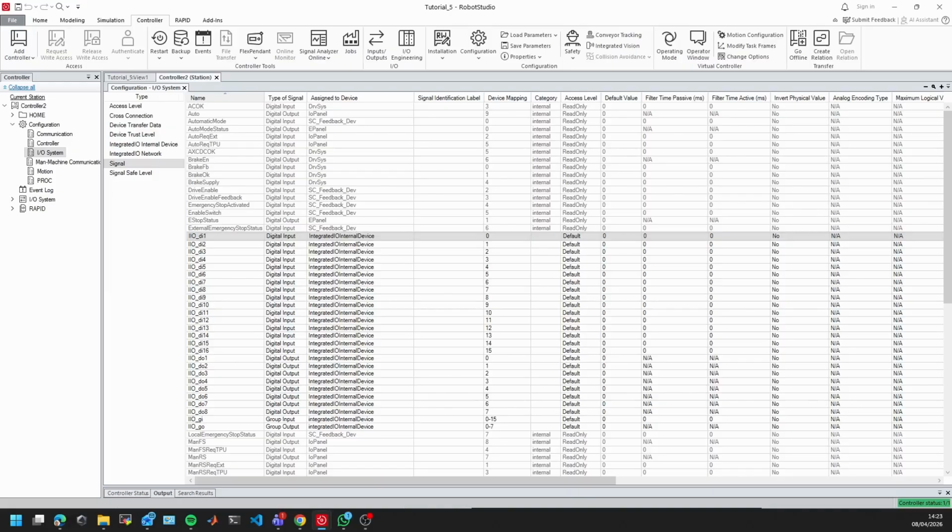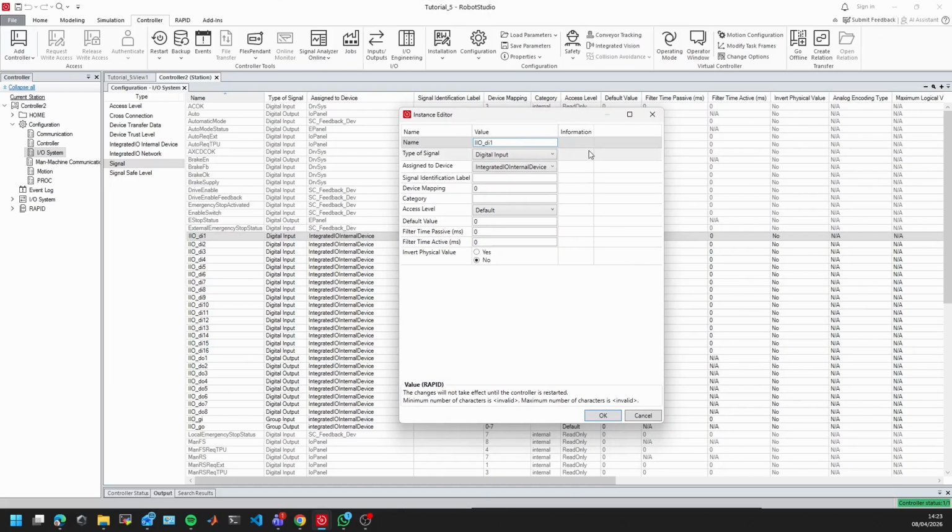And to this end, we're going to create several inputs. For example, let's use this input. Double click on it. A pop-up window will appear. And let's put a name to this one. Let's put a name like, for example, conveyor position peak. Conveyor position is better. I can put a description. I can just copy paste this as a description. Here we go, the description.